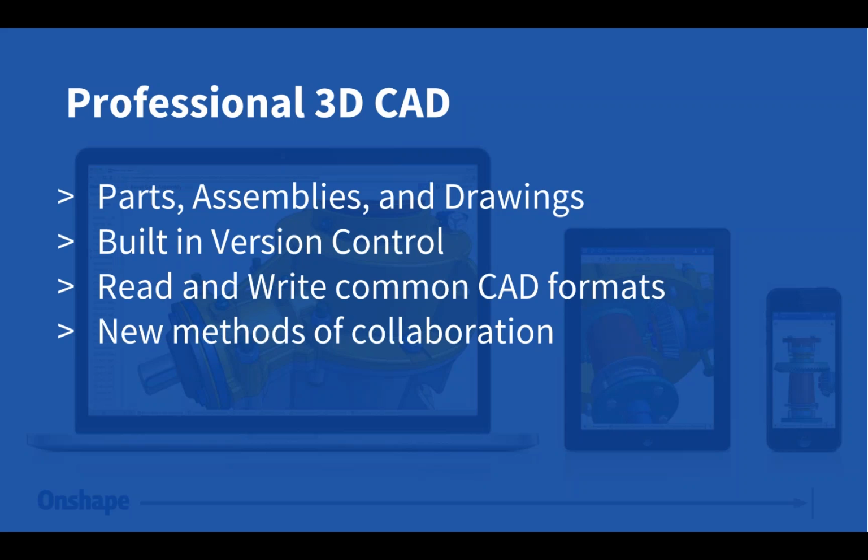So in other words, when you import a SOLIDWORKS part, for example, you will not see the sketches and features that make up that part. And that's just because we don't have the exact same functions and features. We might do something just slightly different in Onshape, and there's no direct way to map the features from one system to another. So it is worth pointing out all those file formats come in as a solid body. They do not come in as a feature tree.